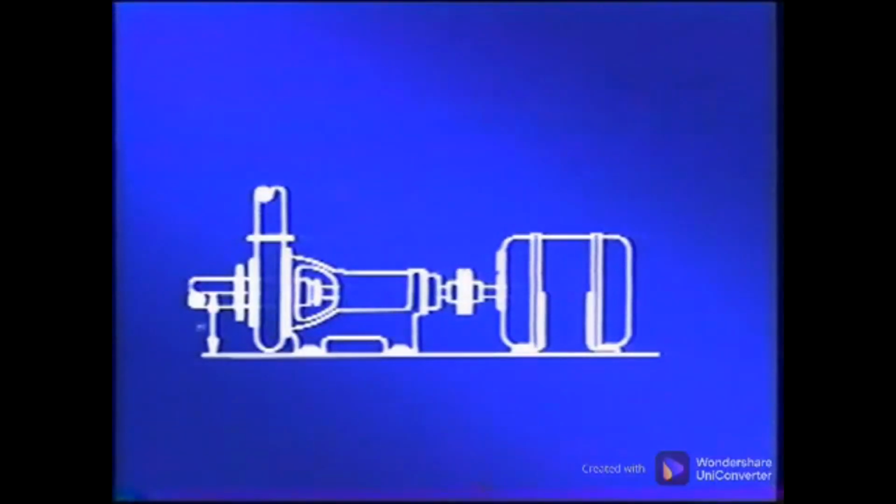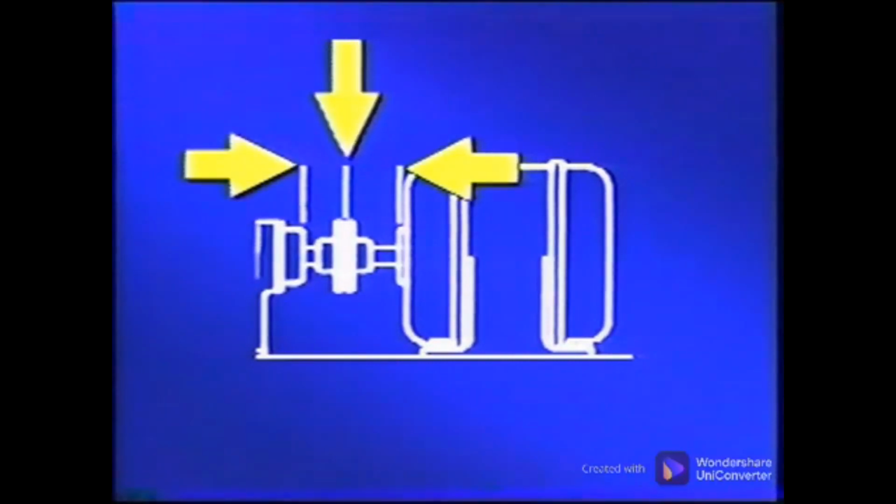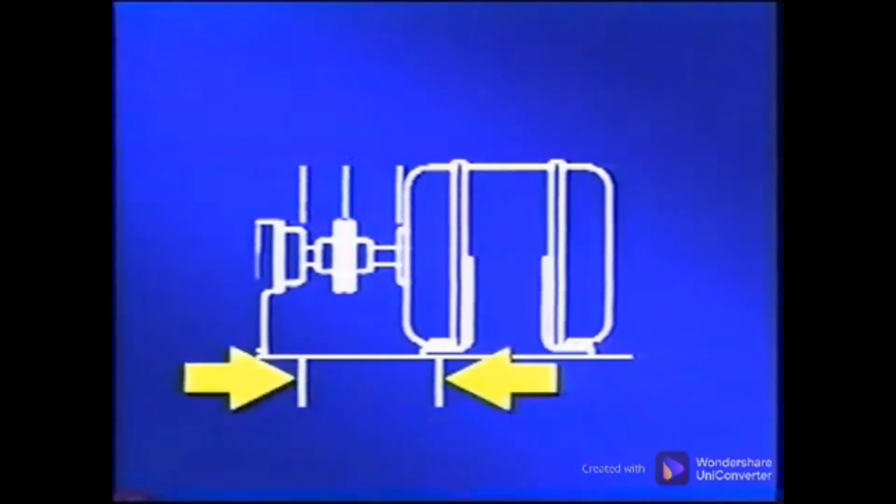Since the corrective moves are calculated for the foot locations, accurate dimensions must be recorded. Measurements must include the distance from the center of the hub to the dial location, from the dial location to the bolts on the inboard feet, and the distance between feet. These measurements should be accurate within 1/8 inch.